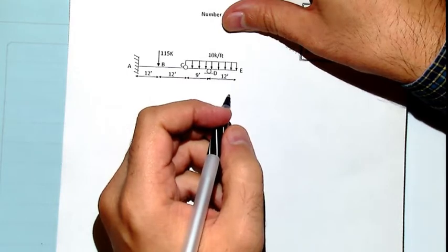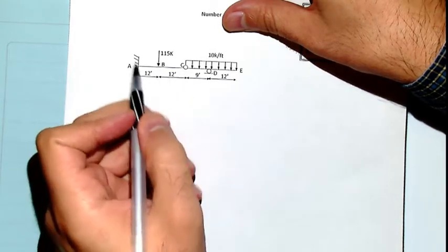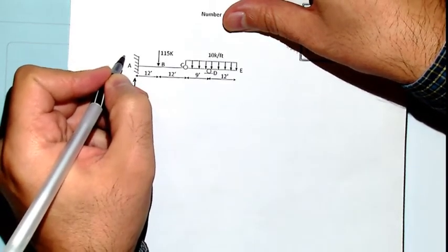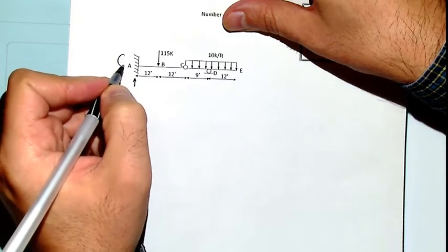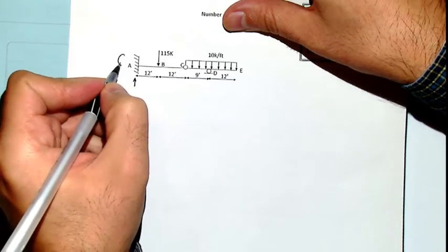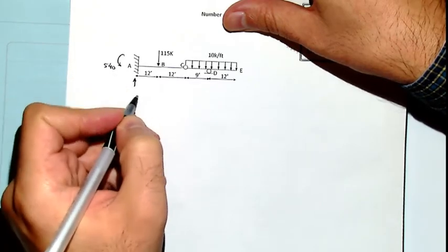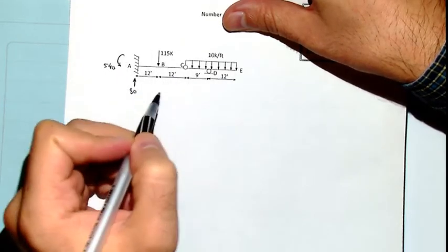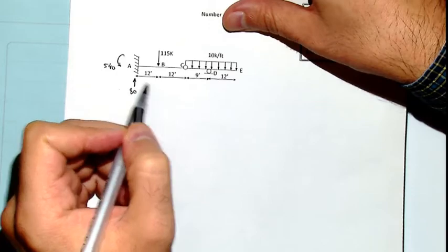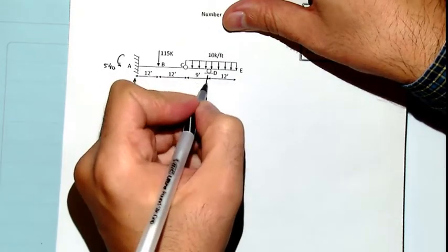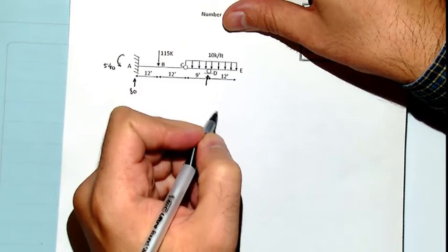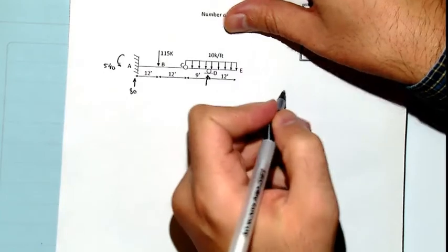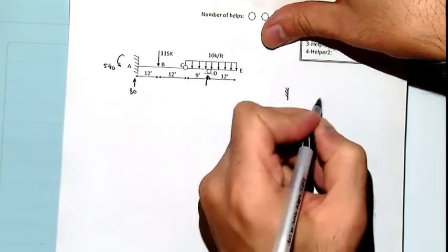It's very important to know how to derive the reactions because we have one reaction here and one moment here. After calculation, it would be 540 and 80. The best way for calculating these sort of questions, because we have 1, 2, 3 unknowns, it might be a little bit difficult, but this hinge helps you to detach this structure from the right side. So the best way would be like this.